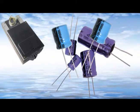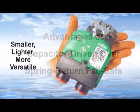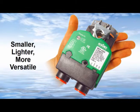Capacitors are electronic devices that store electric charge and require very little current to remain continuously charged whenever power is applied. When electric power fails, the charge in the capacitor is used to drive the actuator back to its home position. Capacitor-driven fail-safe models provide multiple advantages over spring-driven actuators. Capacitor-driven actuators usually have smaller cases, weigh less, and can attach to shorter shafts than bulkier spring returns.